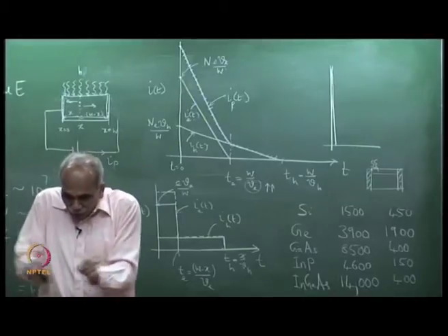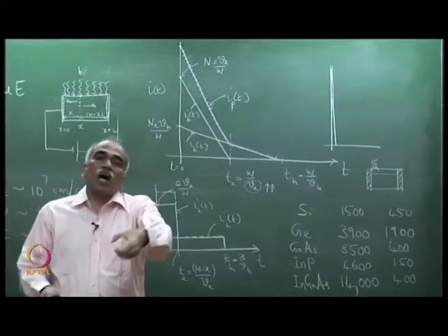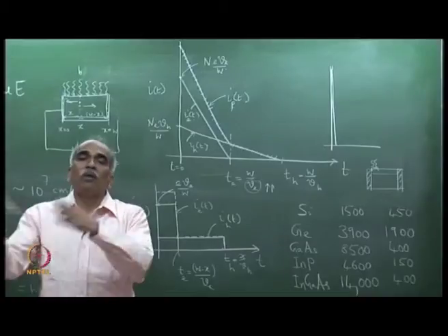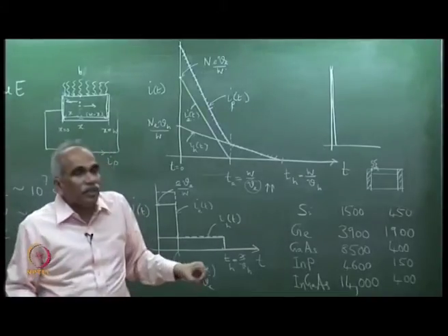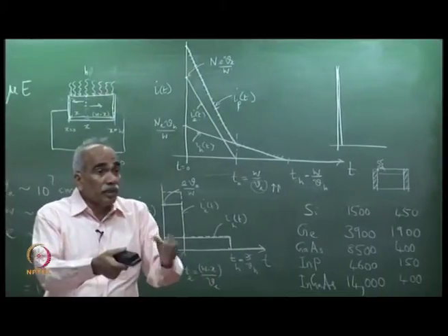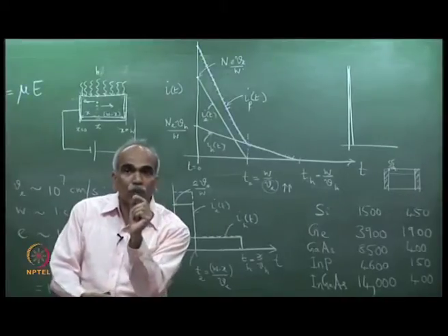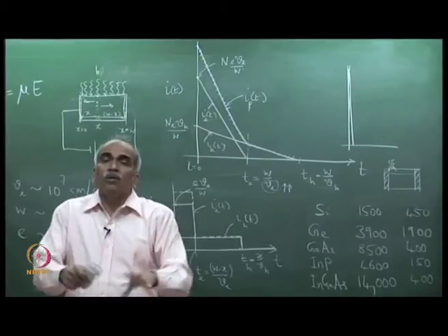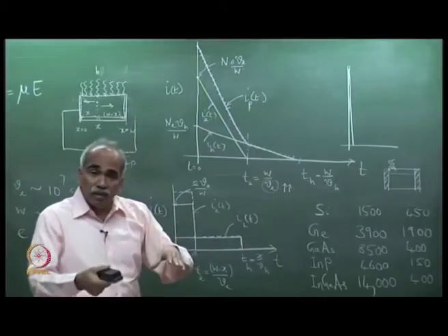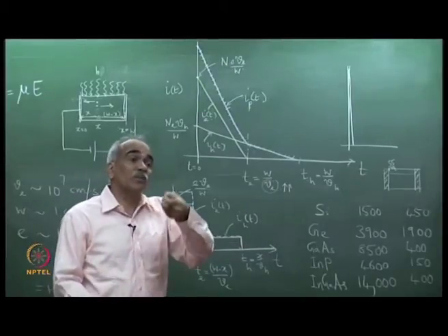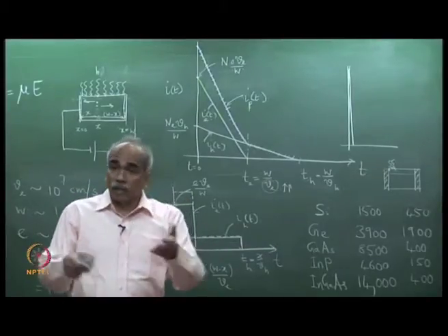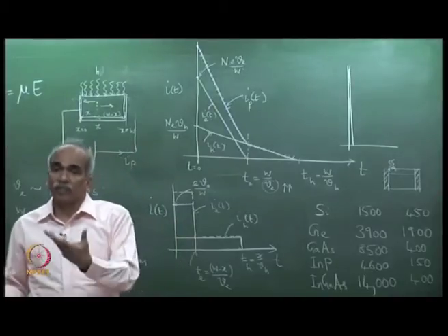The detector should be very small, not a large detector which we use with the normal power meters. You have a large area detector, but all high speed detectors will have a very, very small area, because this is one reason. There is another reason, because smaller the area, smaller will be the junction capacitance, and the capacitance also determines the speed of response.